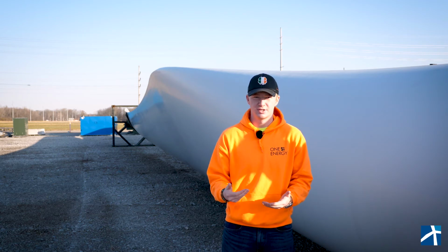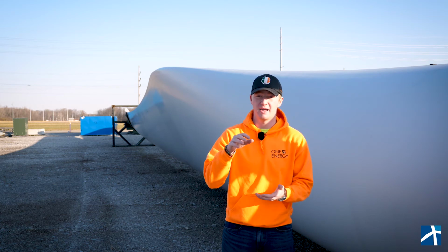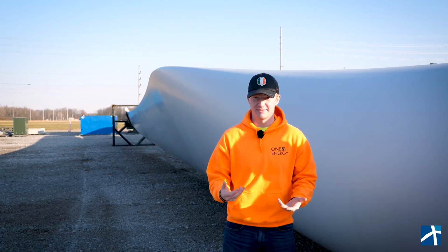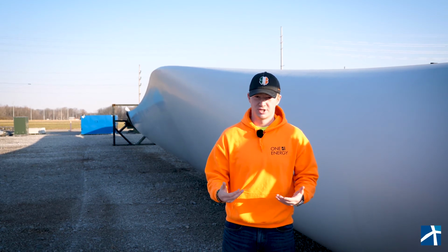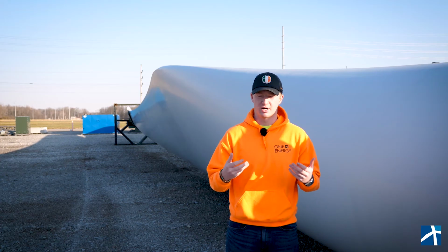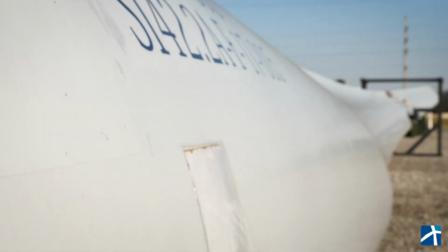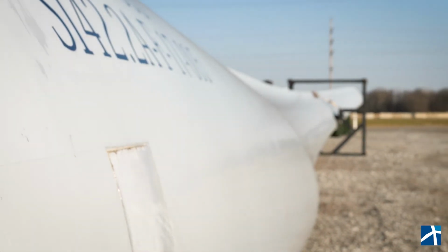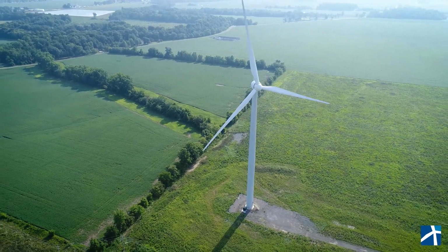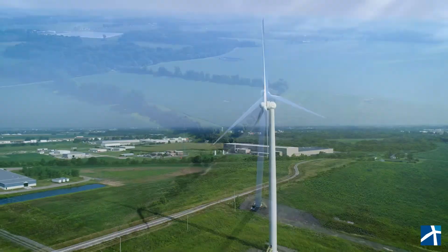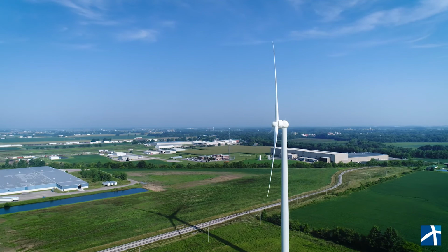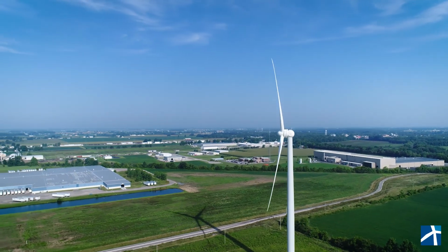These speed differences create pressure differences above and below the blade. These differences are what creates lift, and this is what pushes the blades to move. When someone says wind turbine blades are designed to specifically catch the wind, they're just designed to create lift so that these blades can start spinning and making energy. Lift causes these three turbine blades to rotate. The spinning rotor is connected to the generator, which in turn produces electricity. Power can be used to turn on a light bulb or run an assembly line.